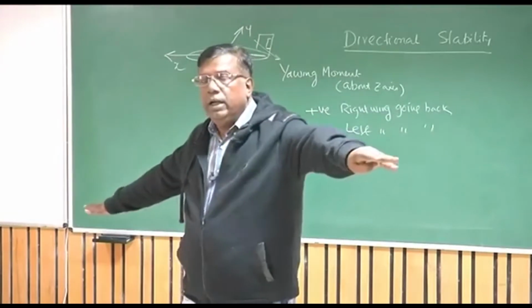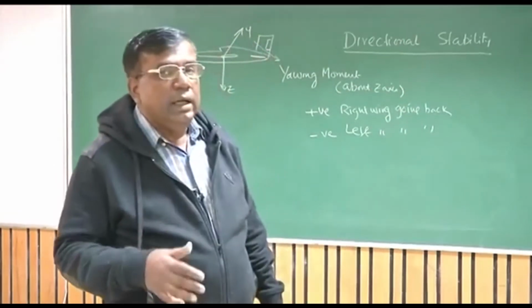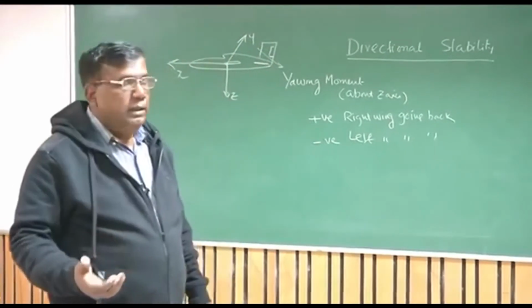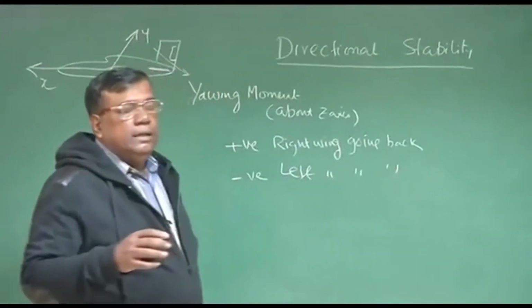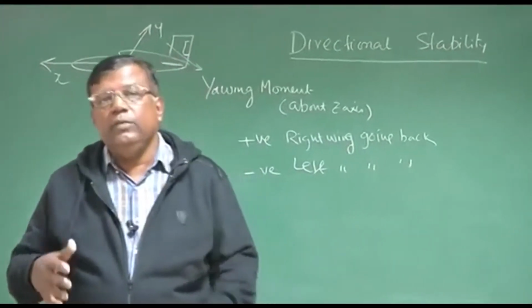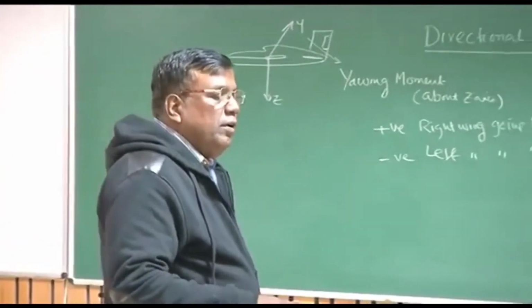As I am yawing, I automatically get banked. So I can say the directional motion and the lateral motion get coupled. But we will be studying directional stability separately, then lateral stability separately, then we will discuss their coupling, etc. This thing will not happen for the longitudinal case.